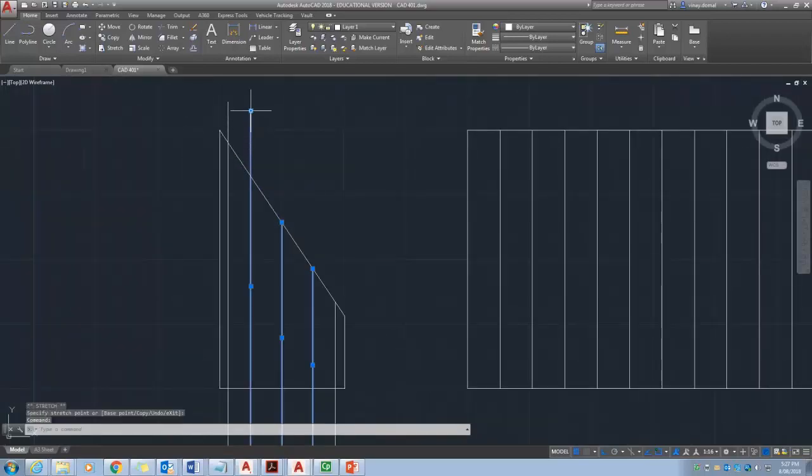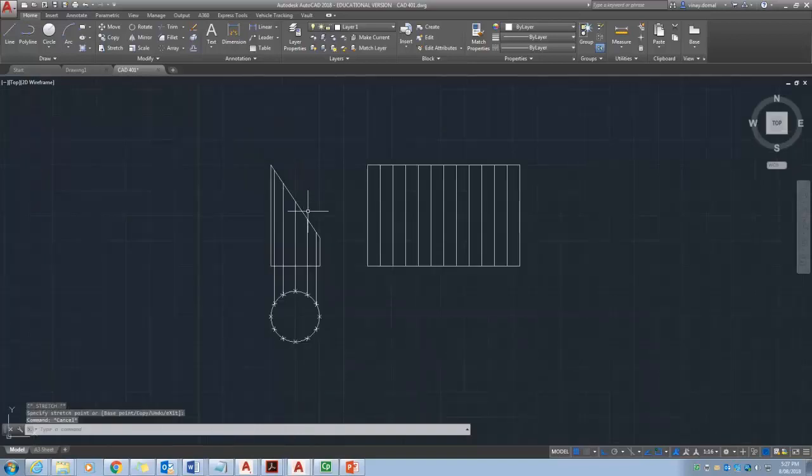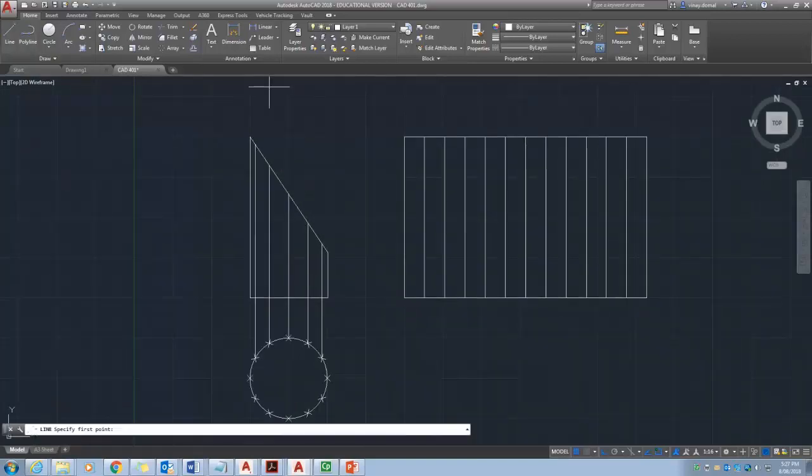So what I'm doing is I have got an extension and I'm finding an intersection on that slope line. So we got the vertical lines ready to be extended further as horizontal towards the rectangle. So just find the perpendicular snap and do all the intersections. So in this case, I think to make it simple, you can also extend up to 6 points this one. So this should be fine here as well.